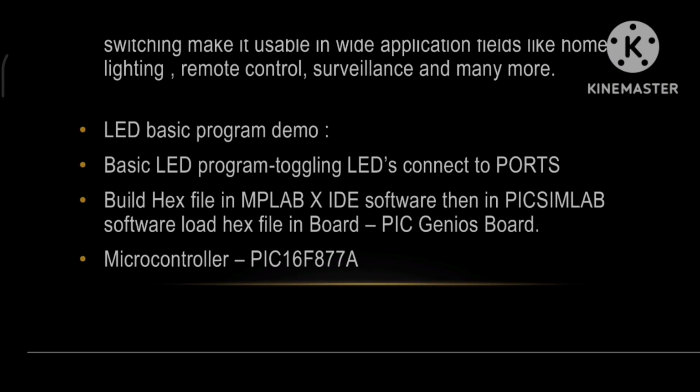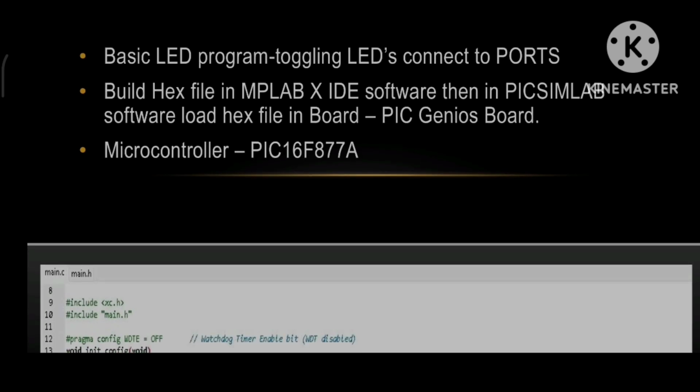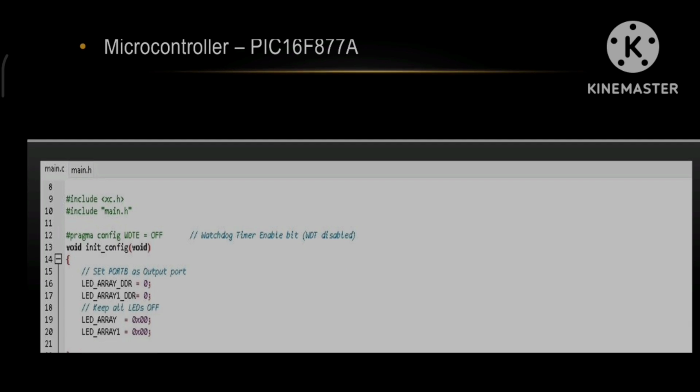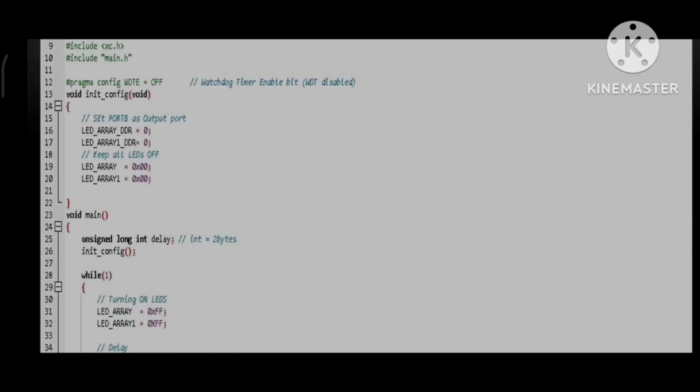LED basic program demo. A basic LED program toggling LEDs connected to ports. Build the hex file in MPLAB X IDE software, then in PIC software, load the hex file in the board, that is the PIC16F877A PICGenios board, microcontroller PIC16F877A. These are the codes for the LED toggling.